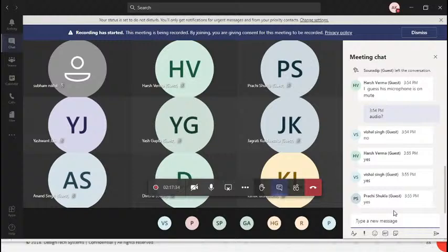So I hope you got how you can use Simulink to design a model for live data: modulation, then designing the channel, demodulation. Further, if you want, you can add some filters there. You can use a relay channel also. Step by step, you can just add it here and play that. That's all. Let me show you one complex example.